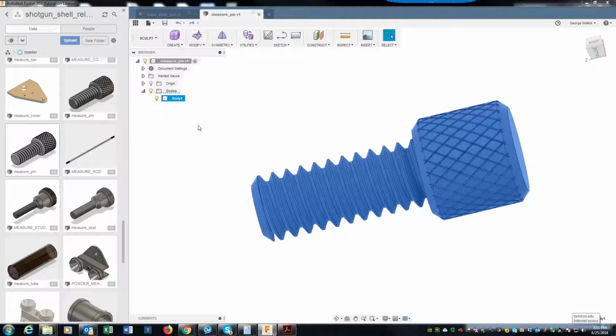Now, obviously, you can do things to it. So if I wanted to drill a hole or cut a slot, it would do that to the model, and obviously, we would see those changes down here. But in terms of being able to easily come in and change the pitch of the threads or whatever by changing the feature, not so much. And Inventor kind of tells you this by looking at the actual model menu up here. It kind of throws you into what's called a sculpt menu, because really none of this is parametric to work with.